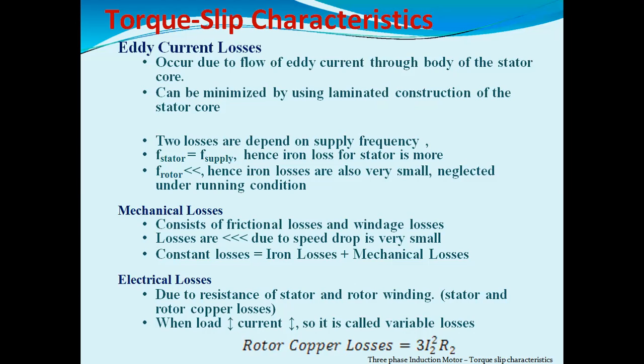Again, if you see iron losses, they will depend on the supply frequency. F stator will be equal to F supply. It means the value of stator frequency will depend on the supply voltage frequency. Hence, iron loss for the stator is more. And if F rotor is much less than F supply, we can say iron losses are also very small, so we can neglect those iron losses.